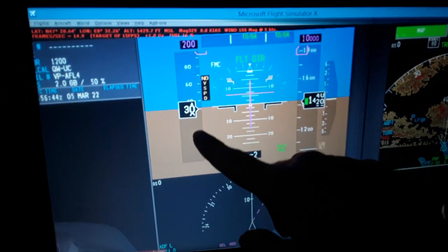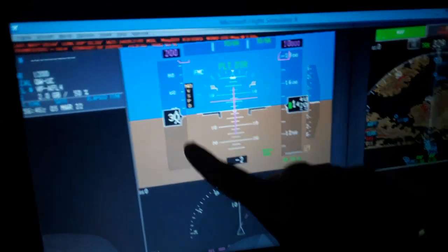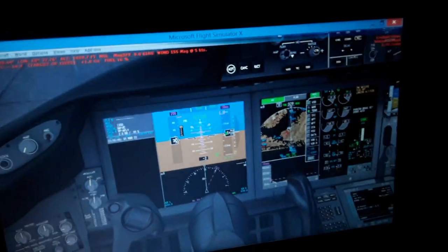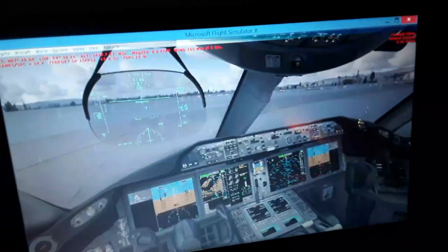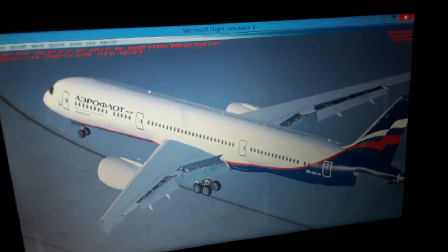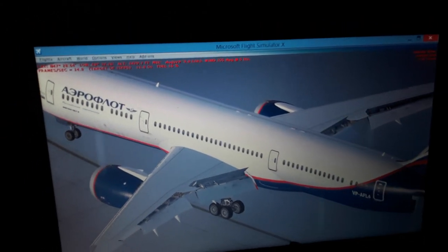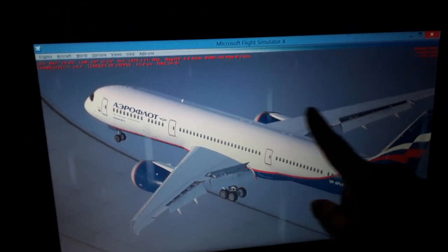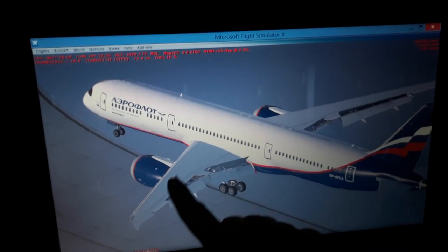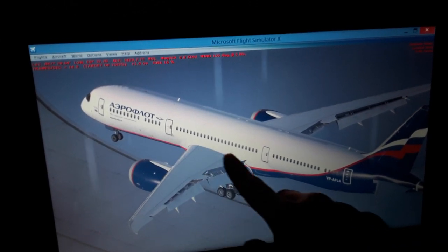We have the stall speed below here with the yellow and red when we fly, and also the angle of attack. So we need to add thrust and pitch down the aircraft when we have stalled. So it stalls from the top surface. Over here with the mean aerodynamic chord is also where the center of pressure is moving forward and aft when we fly.